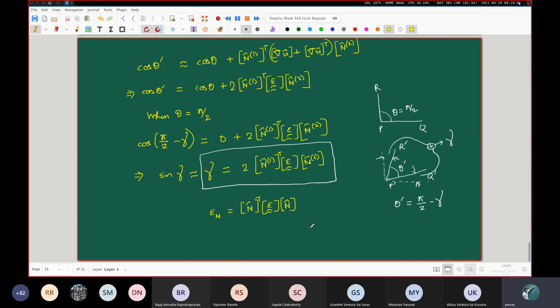All right. So next, what we are going to do is exactly something analogous to what we did in the topic of stresses. In the topic of transformation of stress, we first obtained the general 3-dimensional expressions for sigma nn, and then we specialized to the 2-dimensional version by considering the special case of plane stress. We considered a plate-like structure under a certain kind of loading, and we said that this is a very common engineering situation, and this gives rise to plane stress, where sigma zz equal to 0, tau zy equal to 0, and tau xz equal to 0.